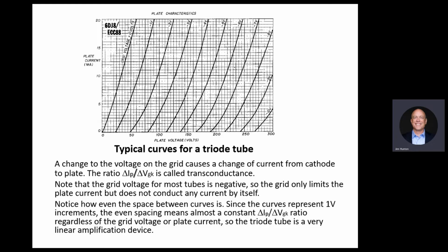It's going to give you very good amplification without distortion. We will show distortion later. If the inherent distortion of a triode, like a 6DJ8, is very low, we don't have to fix it. We can live without negative feedback that fixes distortion, and things like that. And there's some sonic effect to every decision you make.